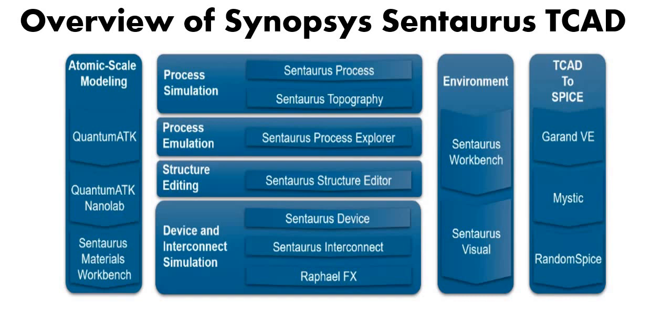It is a bundle of all the environments in one go. It navigates and automates the typical tasks associated with running TCAD simulations, such as managing the information flow, including the pre-processing of user input files, optimization and, at last, visualization of results.